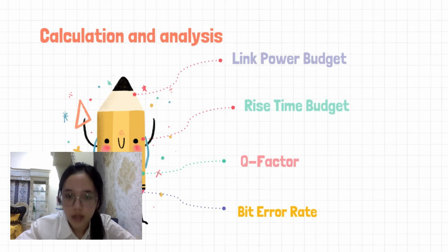Because the power received, which is minus 10.94 dBm, is greater than the sensitivity, which is minus 28 dBm that we got from the planning parameters, we can say that our link is good. Next is the link power budget curve toward the distance.